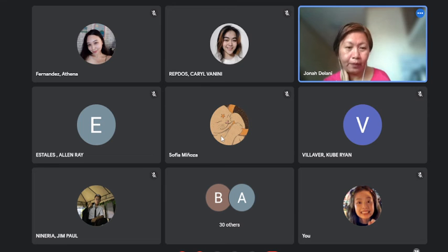However, in the practical world, there is a voltage that can be measured across the diode. It is only very small. If our diode is a silicon diode, it's around 0.65 or 0.7 volts. That's right. The approximate model is in section 9.7.